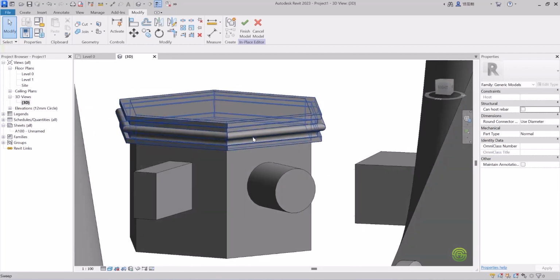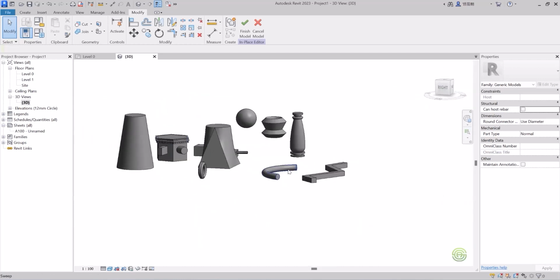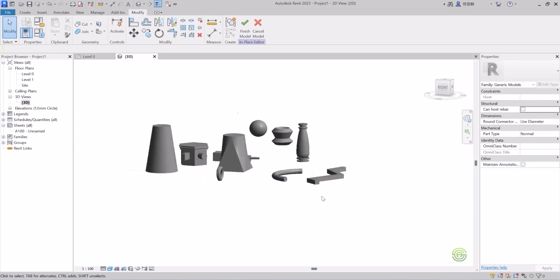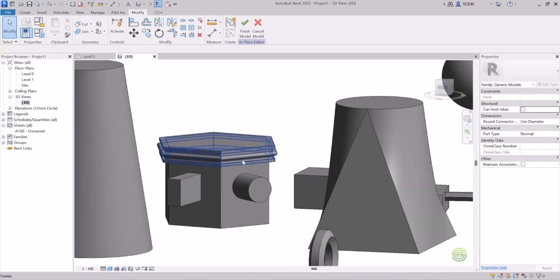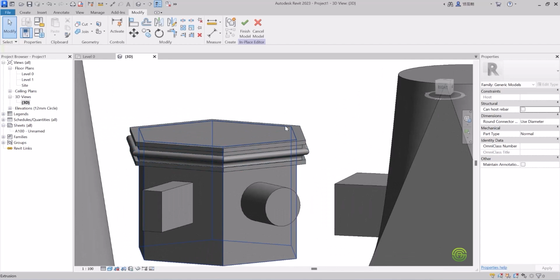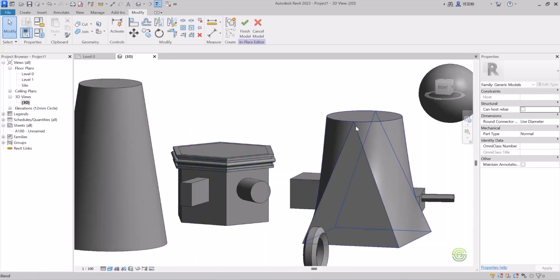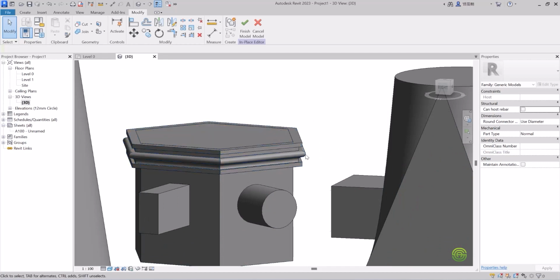So this is the second method of sweep. One method is sketch a path. By creating a new path by sketching, we can apply the sweep. And another method is to pick a path along the 3D object which you have already created. You can just pick the path one by one. If it is a square, you can just pick a path one by one, or a polygon, same thing. If it is a circle, with one click the whole circle will be selected. And then you have to draw a profile. And after drawing a profile, you just have to click on the green tick, and the sweep command will work.